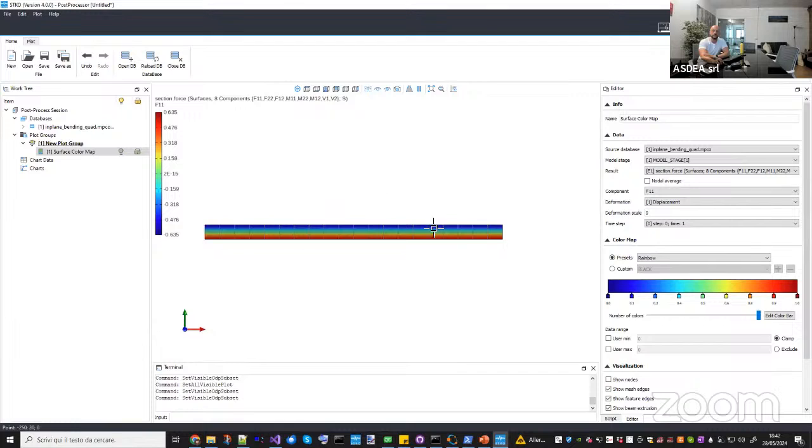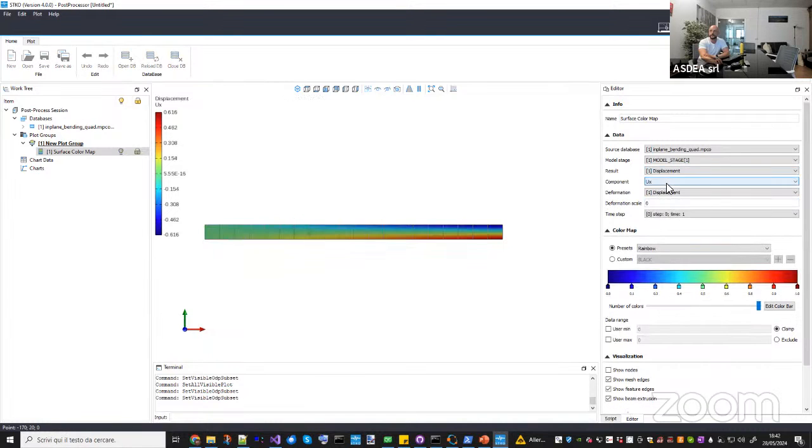So I isolate this one. You will see that the stress is almost 1/2 of the exact solution. And in terms of displacement, you have 12, once again, almost 1/2 of the expected solution, okay? But this is known, okay? So we know that a linear displacement-based element has an almost constant stress distribution and is not able to represent bending properly. So you need a quite good discretization, okay?